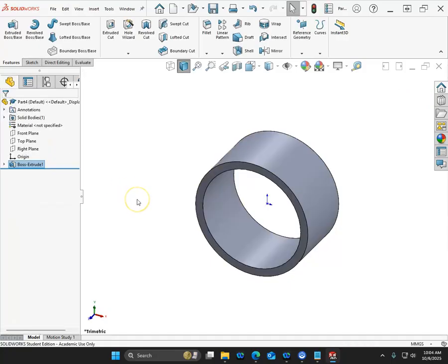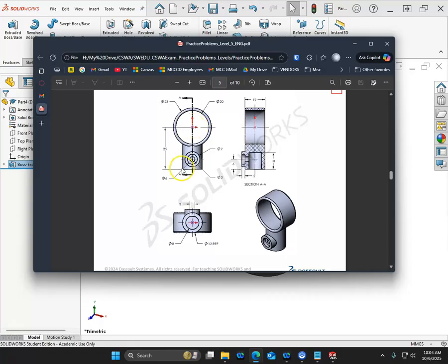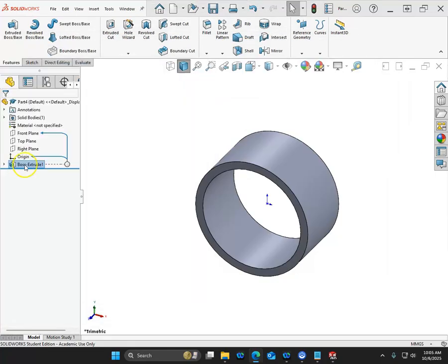All right, so I don't want to put the fillets on until later. Okay, so where you might want to do a plane is from this dimension down 25 and then bring it extruded back up. Because we have the from and to, my first instinct is just to say we're going to go 25 and from. Go ahead and draw the sketch here in the top plane from 25 millimeters offset and up to surface going the other way. But since we're doing planes, we'll go ahead and do the plane.